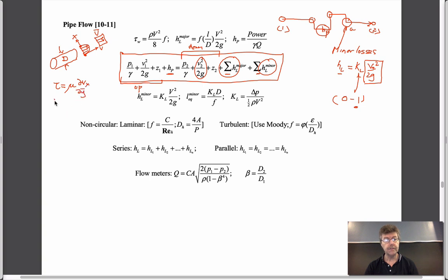And so, in other words, if you look at the velocity profile relative to this surface, this is just a consequence of this expression here. It says that our boundary condition pins the velocity at zero here. Right next door to it, it's sliding over it slightly faster. It's controlled by this expression, which we don't need to solve.